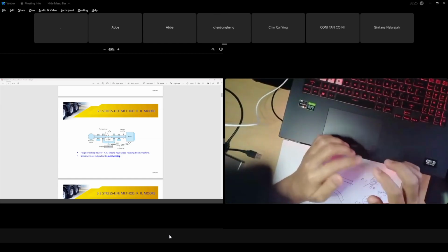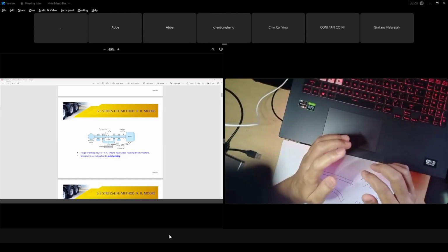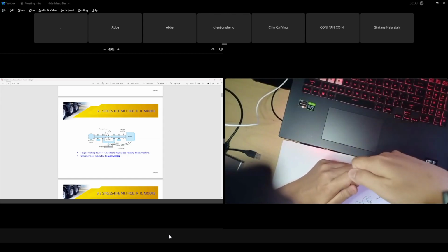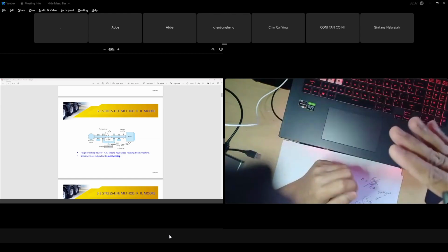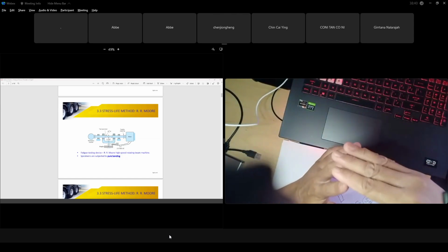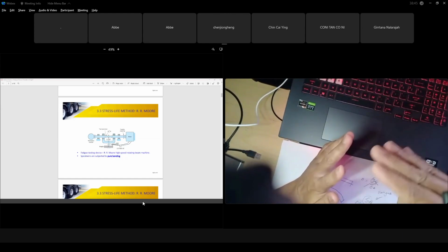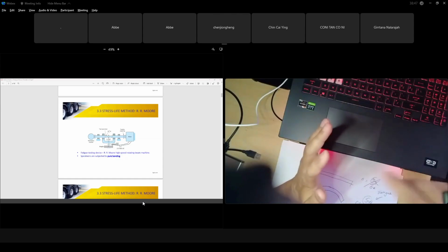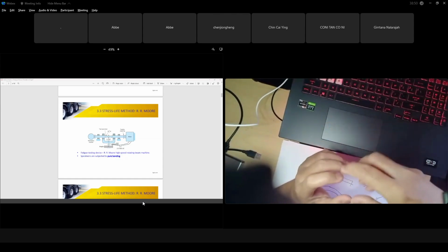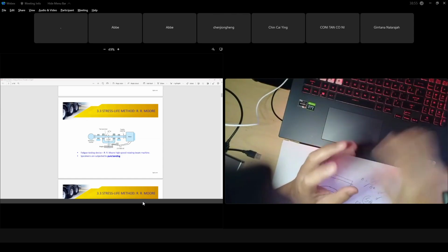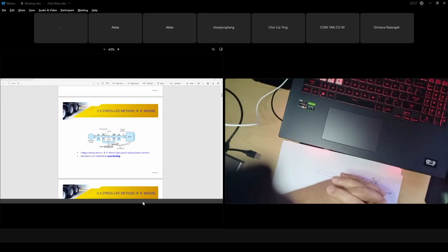Because remember, when you do static analysis, you will refer to the Sy value. For the Sy value, engineers already did the pure tension test with a universal tension machine. They push your specimen, then you record all the data, including the value of the force. For axial loading, this force is used to calculate the axial stress, up until the yielding value, Sy. After Sy, the ductile material behaves with plastic behavior, so it is no longer safe. Dah jadi lembik. After you reach the Sy value, that one is for static.